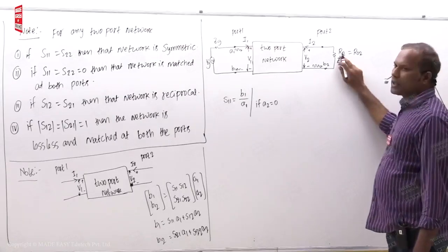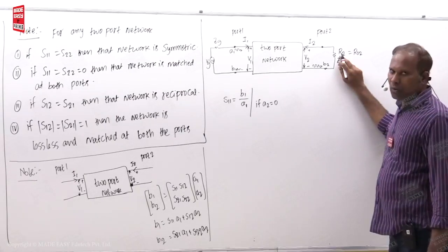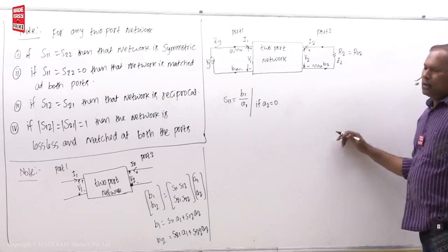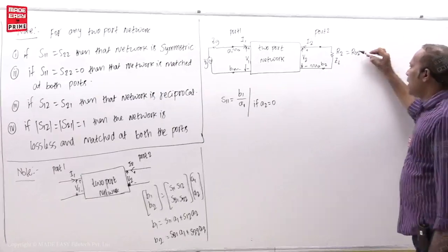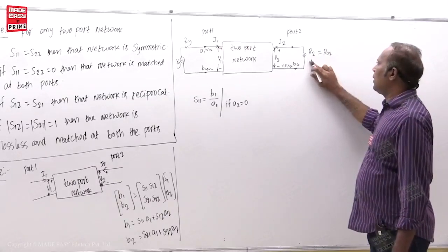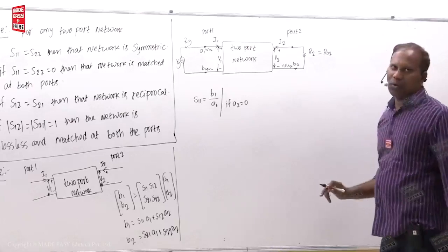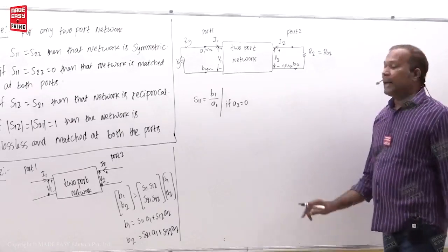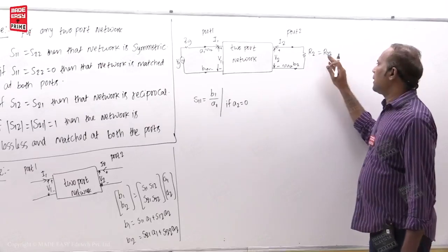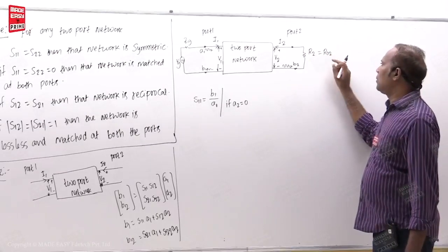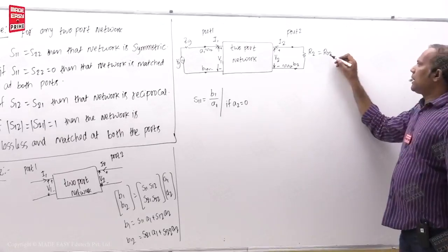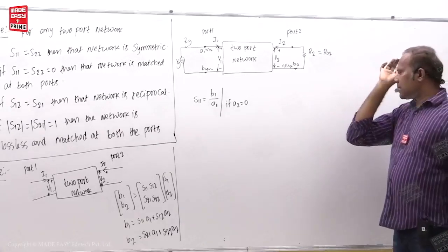So similarly, R2 is a terminating impedance at port 2, and this is called the reference impedance at port 2. This is a positive value. You can change this. Now in place of ZL, we have put R2. That is, R2 means the terminating impedance at port 2, and we will equate that to the reference impedance at port 2. So you can change this, it is a positive resistance.